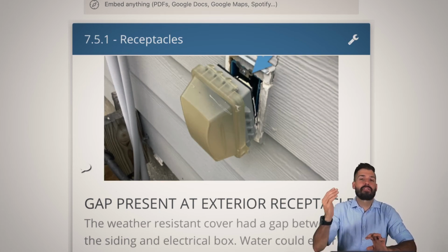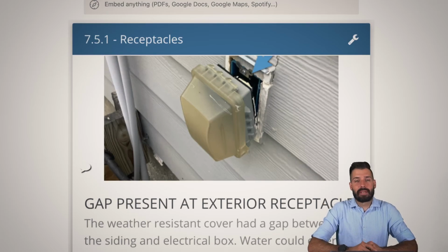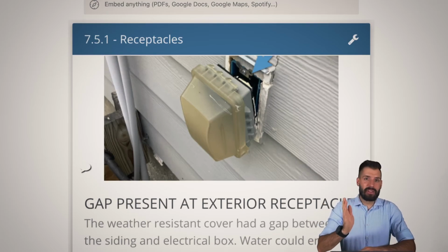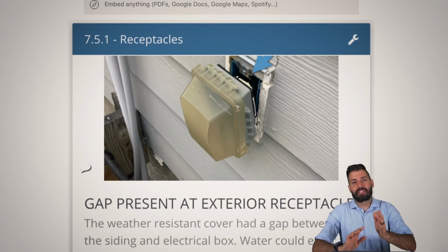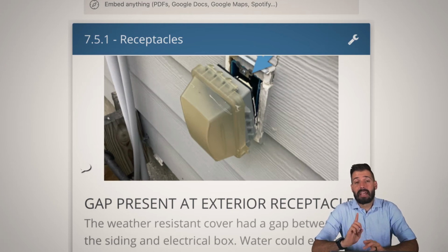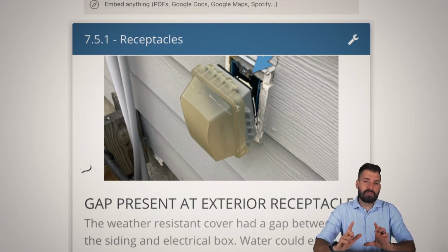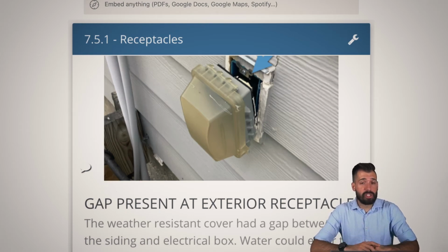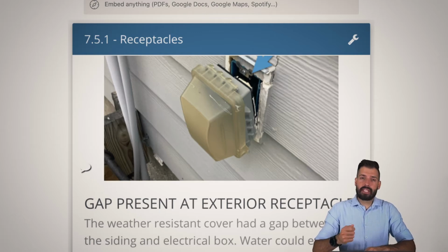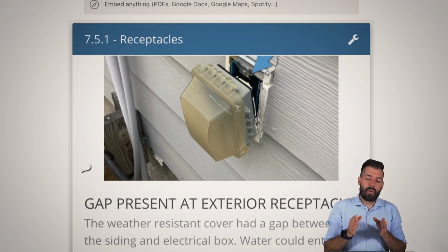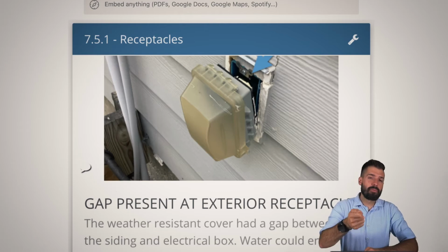It's going to prevent any weather from getting into where that receptacle is. Oh, wait, but behind the weatherproof receptacle is where we're actually getting water coming back in and inside. Now, here's the scary thing, is that this is GFCI protected. But just because it's GFCI protected does not mean that the wires that are currently exposed are GFCI protected, because that GFCI protection is from where the receptacle gives that electricity, where you plug in at.